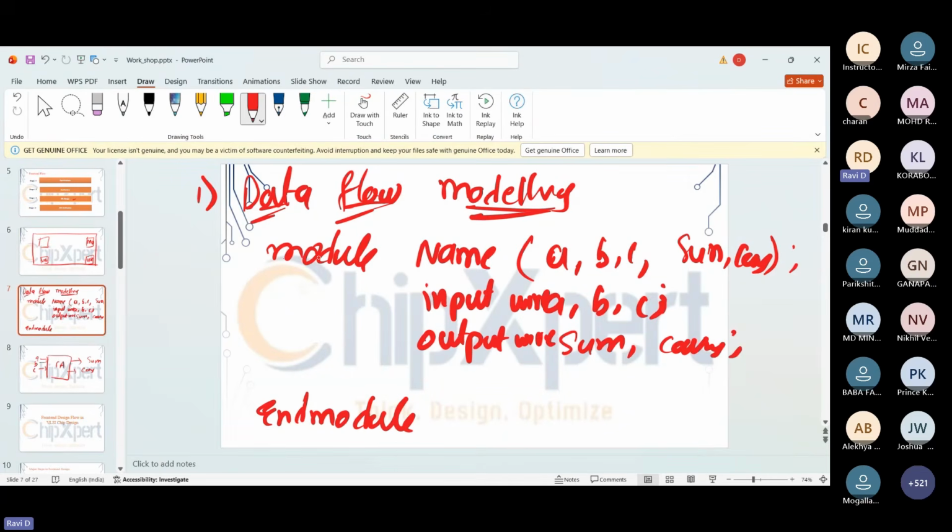You need to design the logic in the form of textual formats. Here I'm using the gate level modeling style, right? When we are designing the code in this style, we write a continuous assignment. Continuous assignment is nothing but continuously driving the data to our outputs. That means we assign data to a wire data type. For declaring that continuous assignment, we use the assign keyword. So assign, and here we write our logic.